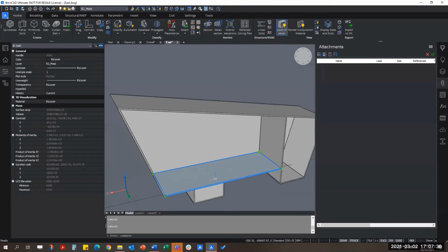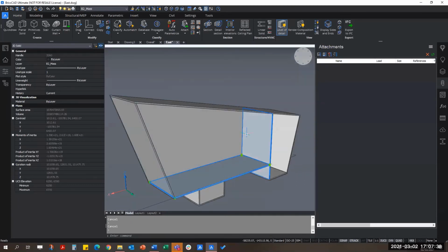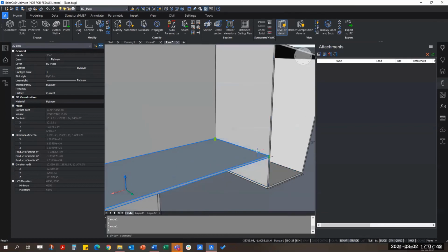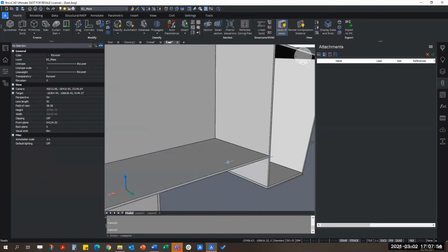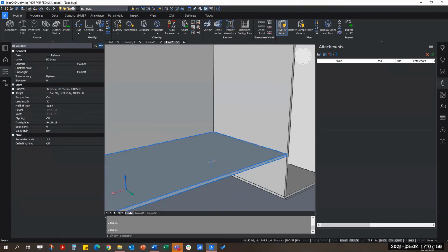Now that I have got this wall set here, I would like to bring this floor plate upwards. I'm going to duplicate maybe 3 or 4 floor slabs up here. And what I could do here is obviously you can revert back to your normal shortcuts, just like as you do with Pro or with BricsCAD Lite, which is copy CO. However, in BricsCAD BIM, we have something called BIM Copy, which essentially copies your selected entity together with its metadata, if applicable.